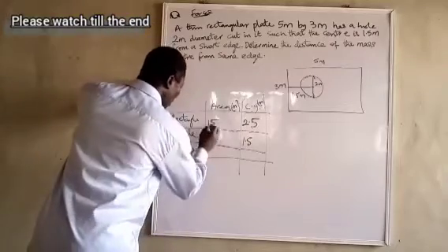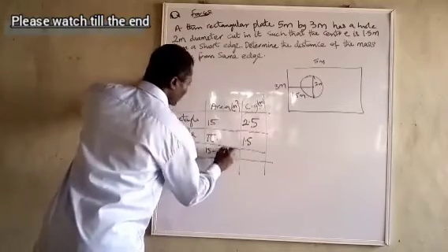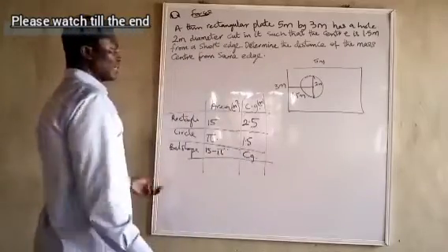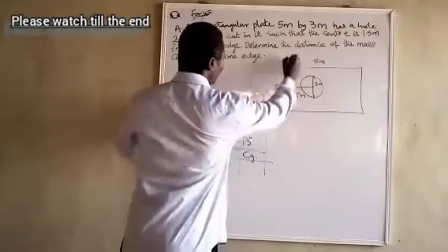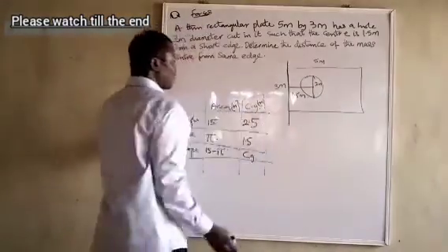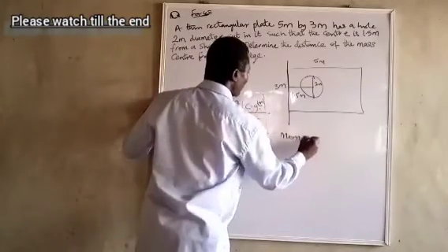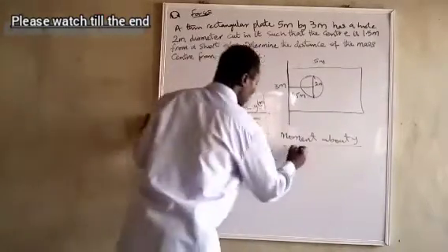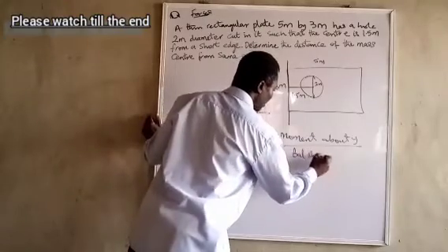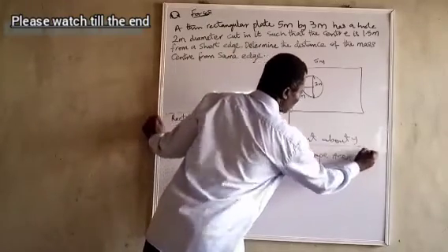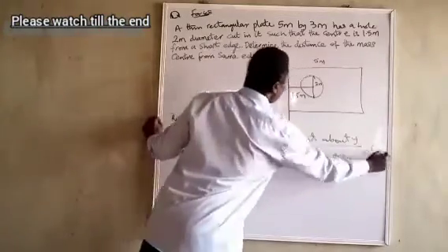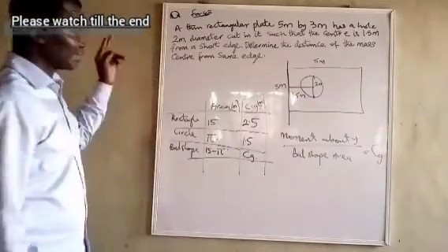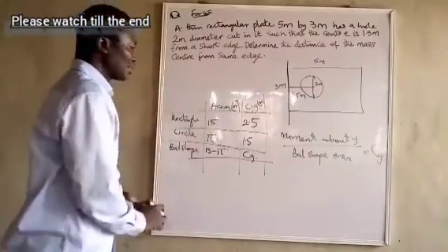The balance shape is going to have area of 15 minus pi meters squared. And the center, let's call that CG. So if we take the moment about y, moment about y divided by balance shape area, we are going to have our CG. Please, we have assumed that it is having constant density all through.